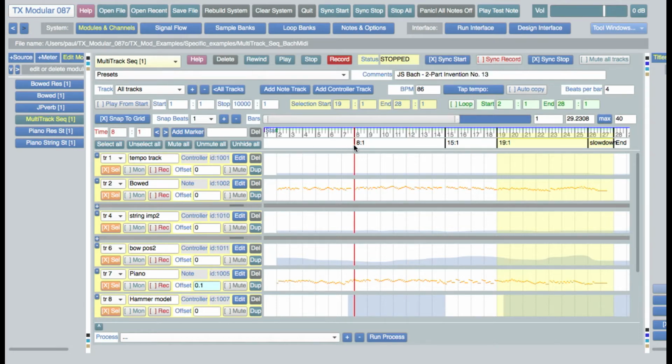If you click and drag in the timeline with the Shift button pressed, the time selection will be changed and colored yellow. One more thing you can do on the timeline is to press Command and drag to change the loop start and end. The green loop line will show the new loop.